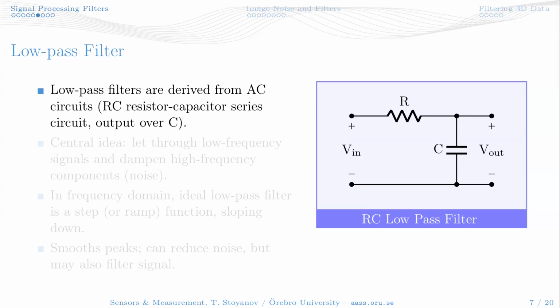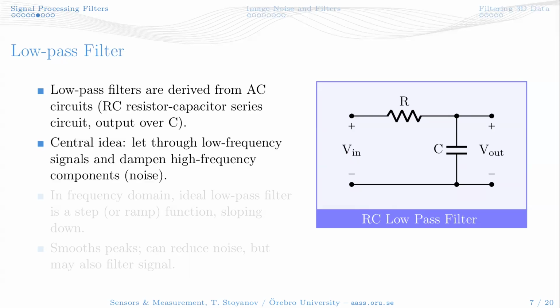What does that do? That essentially smooths out peaks, right? It smooths out peaks because the capacitor there takes time to charge and discharge. So the central idea here is to let through the low frequency components and dampen the high frequency components.